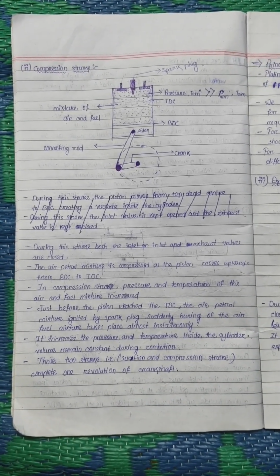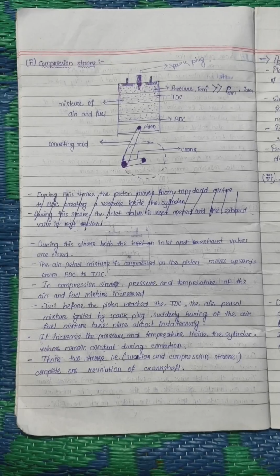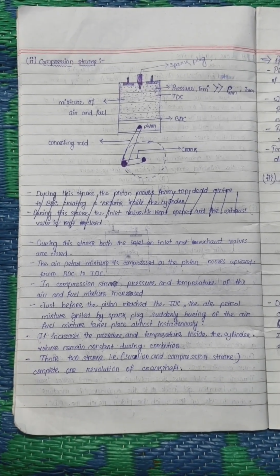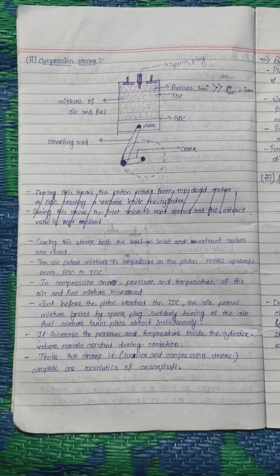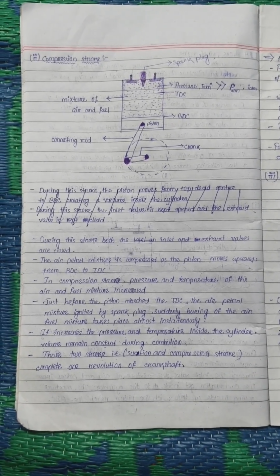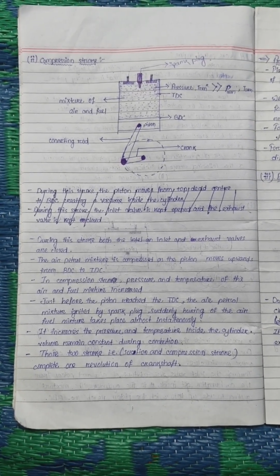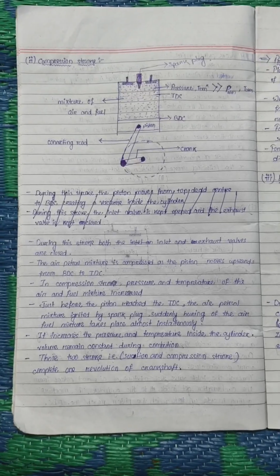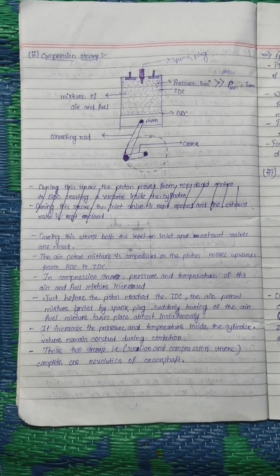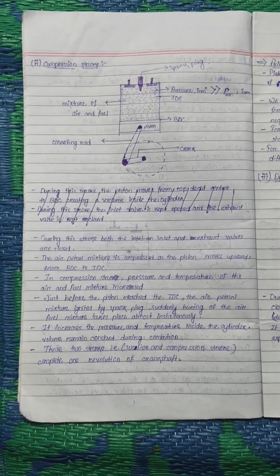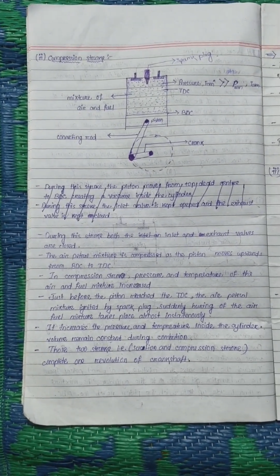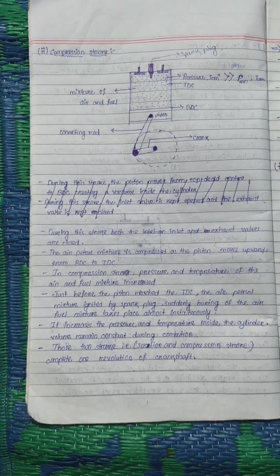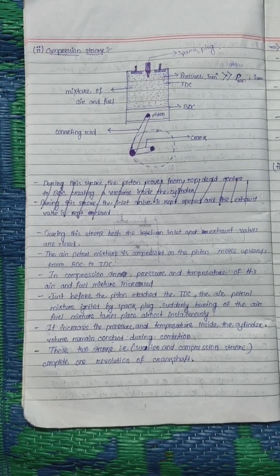Suddenly, burning of the air-fuel mixture takes place almost instantaneously. It increases the pressure and the temperature inside the cylinder. Volume remains constant during the combustion. These two strokes, i.e. suction and compression stroke, complete one revolution of the crankshaft.